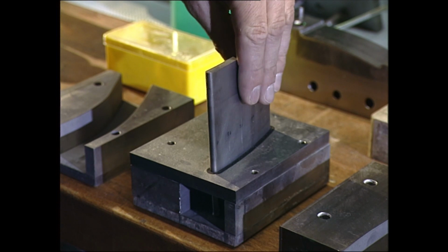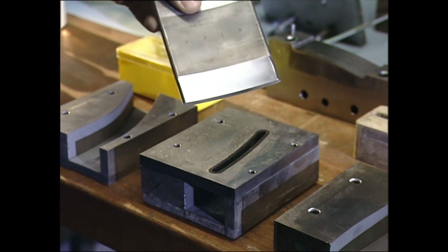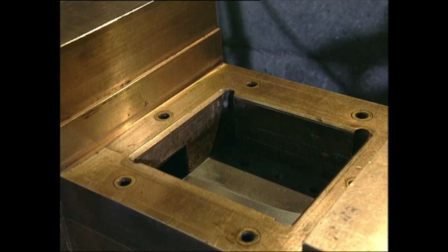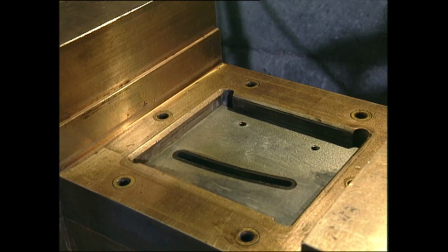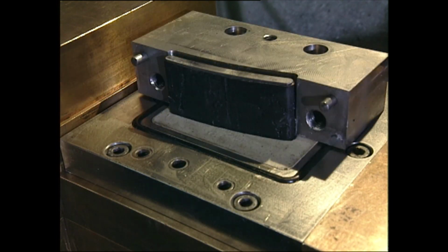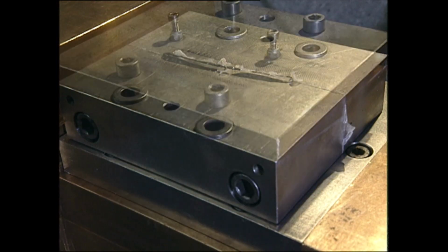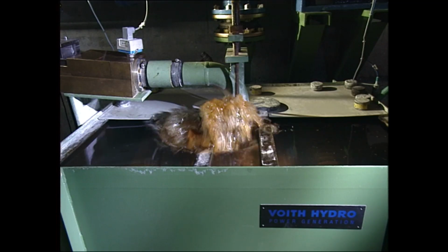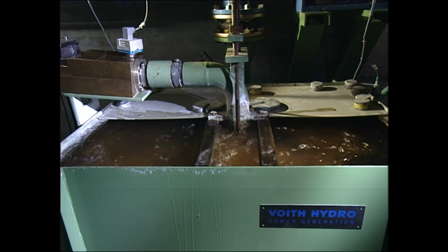Here, the shape of the test bodies corresponds to the geometry of an idealized hydrofoil. The test bodies are inserted into a converging test channel. There are geometry options for different blade curvatures. After insertion into the closed test loop, it's possible to expose the specimen to a clearly defined flow of sand-laden water.